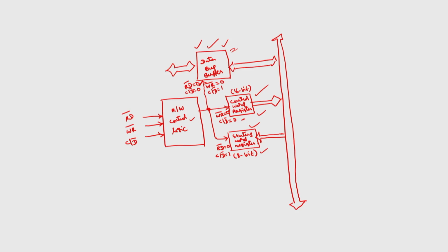Now, what about this 16 bit control word register and status word register? What are the formats of the control word register and status word register? Like in case of other peripheral devices, we have some format which is going to decide the modes of operation and the various details of the transmitter as well as the receiver. The control word register is 16 bit, but again this is independently divided into two 8 bit registers.